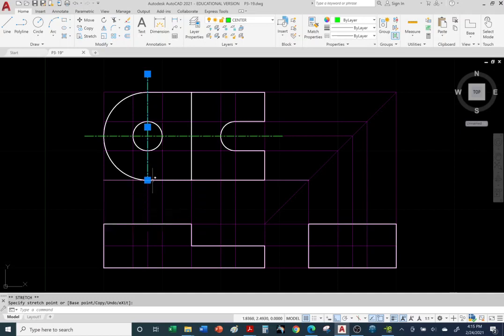Now, the reason it doesn't want to extend is because it tries to snap back to any corner or midpoint. So I'm going to have to temporarily turn off Object Snap. If you're having trouble locating that endpoint, slightly extended, and it's not going to where you want it to go, then you can turn off Object Snap. And you can now freely extend it, as you can see. All right, let's draw one more center line.